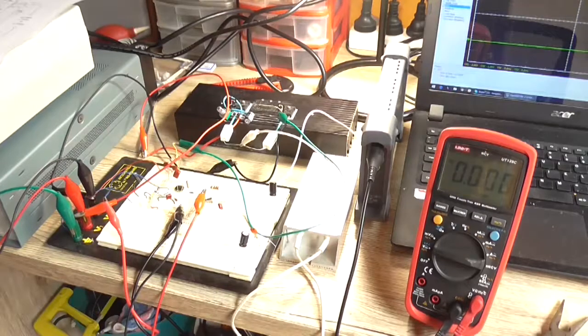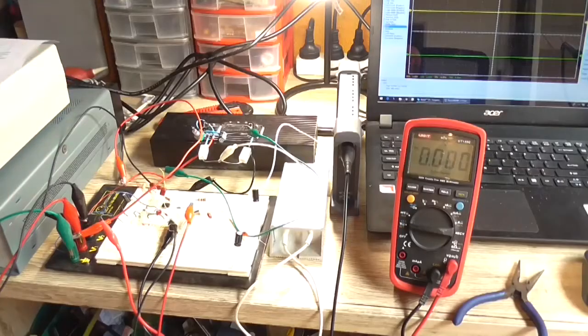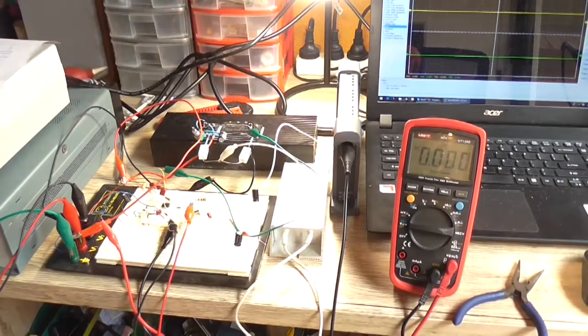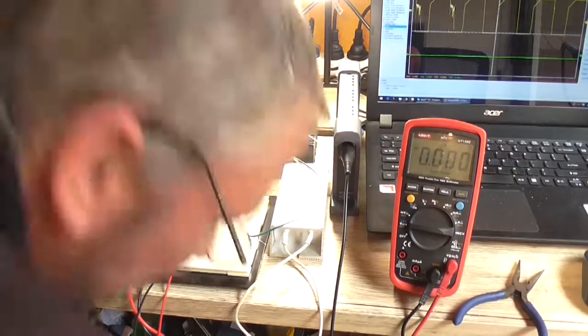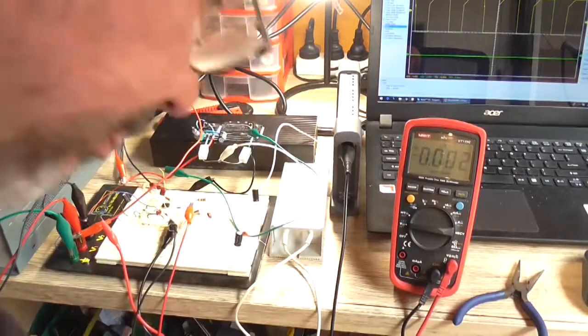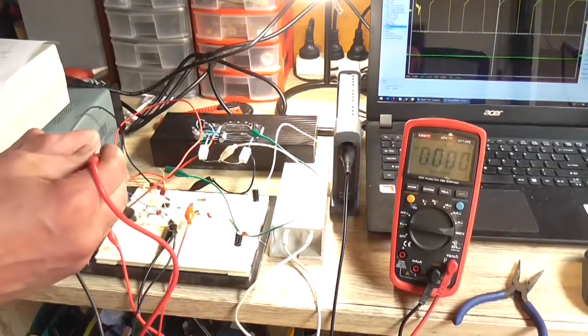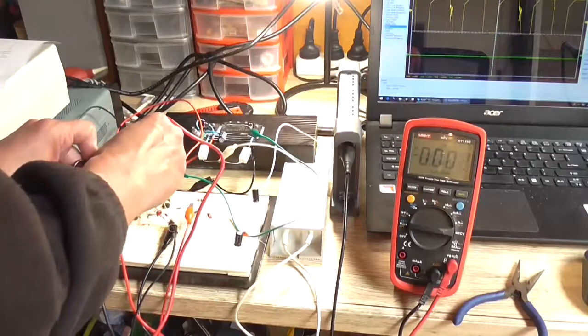Let me make a little modification. Okay, I changed the resistors that I had as the droppers to the Zeners from 2K7 back to 1K, to see if I get a little bit more voltage output. But I think I've actually discovered what the actual problem is, and I'll let you in on that secret in a minute. Let me just find out what our voltage is now.